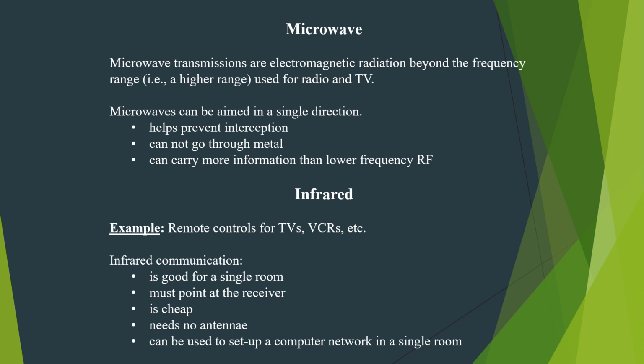The simplest form of microwave link can have only one hop, consisting of one pair of antennas spaced as little as 1 or 2 kilometers apart. It can also act as a backbone, including multiple hops spanning several thousand kilometers. Atmospheric conditions and certain effects modify the propagation of microwaves, so even if the designer can see from point A to point B, a true line of sight, it may not be possible to place antennas at those two points and achieve satisfactory communication performance.